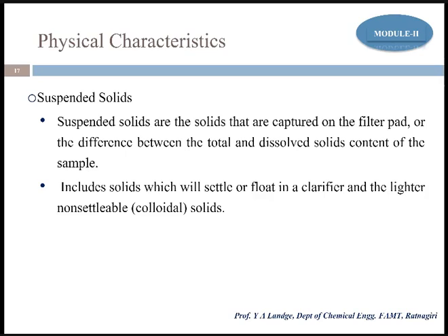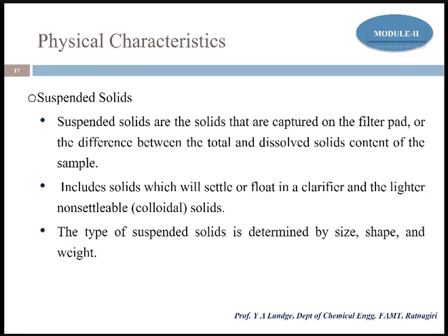Now in the suspended solids, we say that the material is settleable and non-settleable. Those which are lighter in weight are the solids which will settle or float in the clarifier, and the lighter non-settleable solids we call colloids. If you see the suspended solid concentration in the water bodies, it is around 20 milligram per liter.